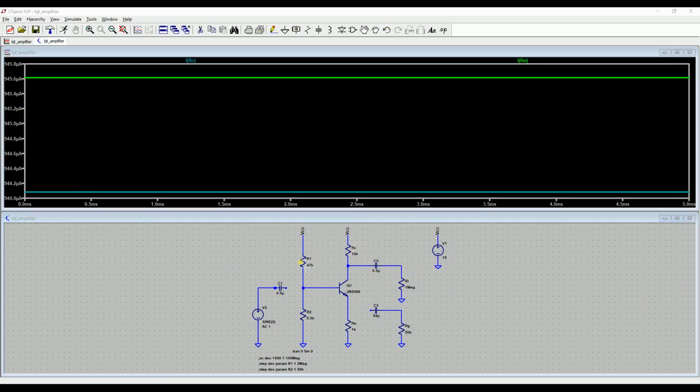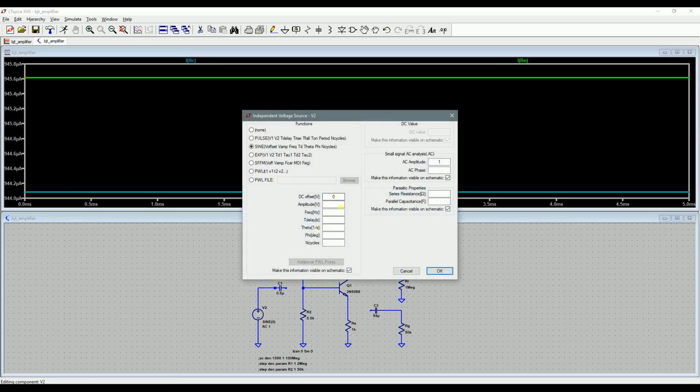So now we're going to choose the value of our AC signal. So we'll go in here and let's say do 1/4 volt just so we don't overshoot. And we'll do 1000 hertz, so we're well over the cutoff frequency that we've chosen, which is pretty much just for DC.